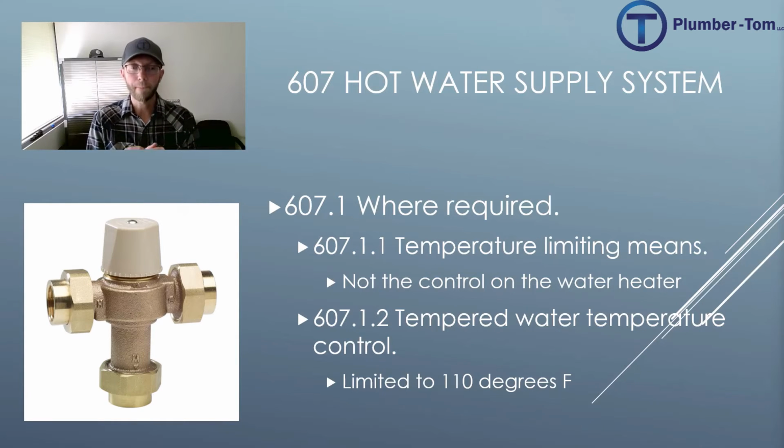607.1.2 talks about the tempered water temperature control. And if we're going to use a temperature limiting valve, then it has to be set to no greater than 110 degrees Fahrenheit. There are a number of standards listed there and options for limiting water temperature.